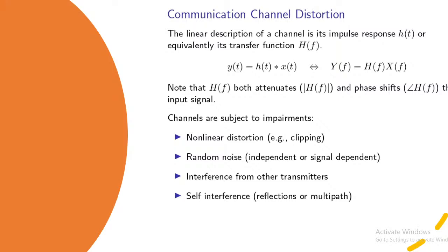Now, in between point A and point B, the signal will be transmitted in all directions by the antenna. Suppose at point C there is a reflector, an obstacle, or some object. The signal goes from point A to point C, then it gets scattered and the scattered part comes to point B. Similarly, the signal from A directly comes to point B.